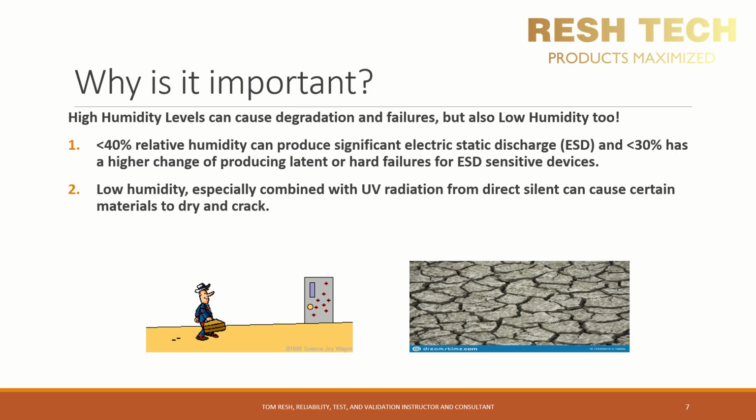ESD can be a killer in electronics, and I will be dedicating a video to ESD testing later on in this series, with more details on the physics of ESD and how to perform ESD testing. Additionally, low humidity, especially when combined with ultraviolet light, can cause materials to dry and crack, which can be cosmetic damage at a minimum, or even cause your system to lose its functionality, sealing, and can even cause safety issues.